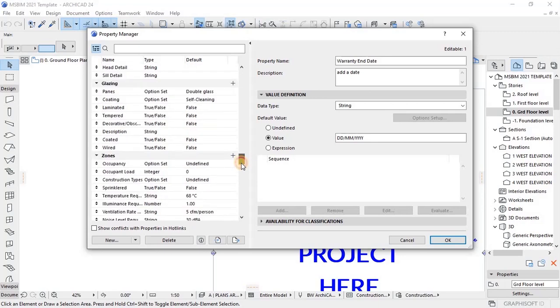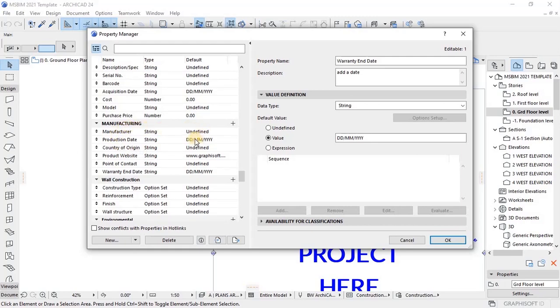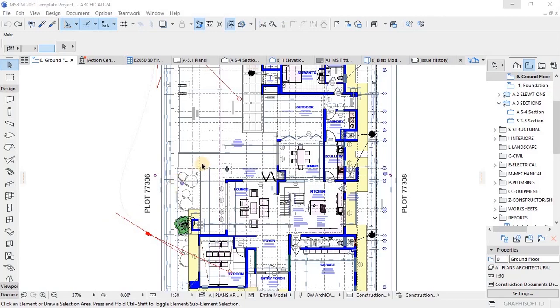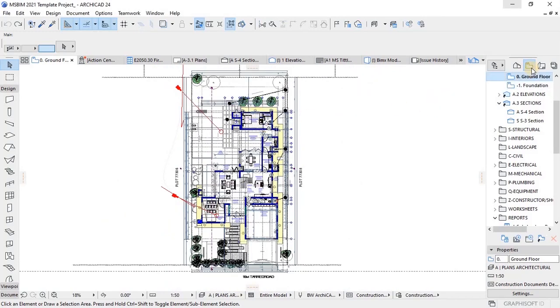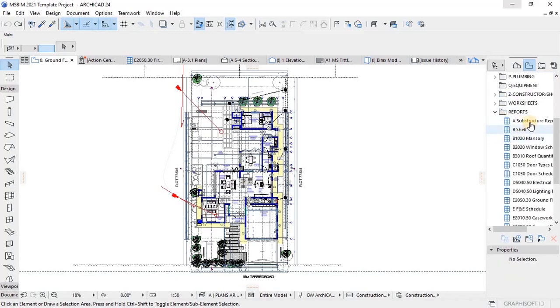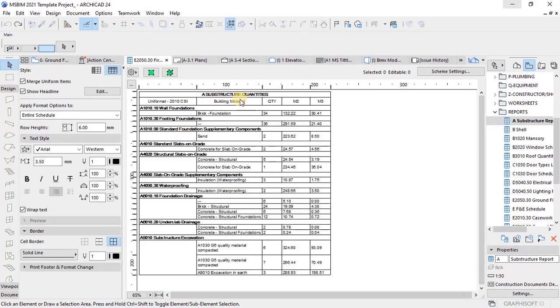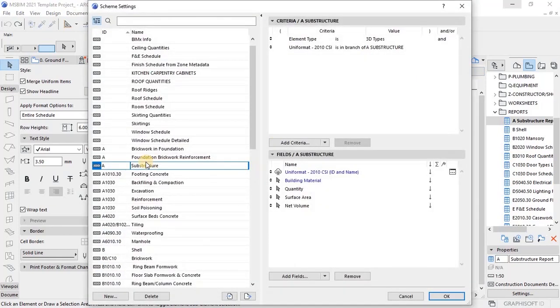Let's say you go to a slab, and then you check the properties of a slab that we have, and then edit, and then check the information that we have, check the availability of the properties that we have. We wouldn't have every property associated with that. That's how you define it, by edit, and then enable those checkboxes. And then here you could go to option setup, and then you add more information. Right now this is how we define our slabs.